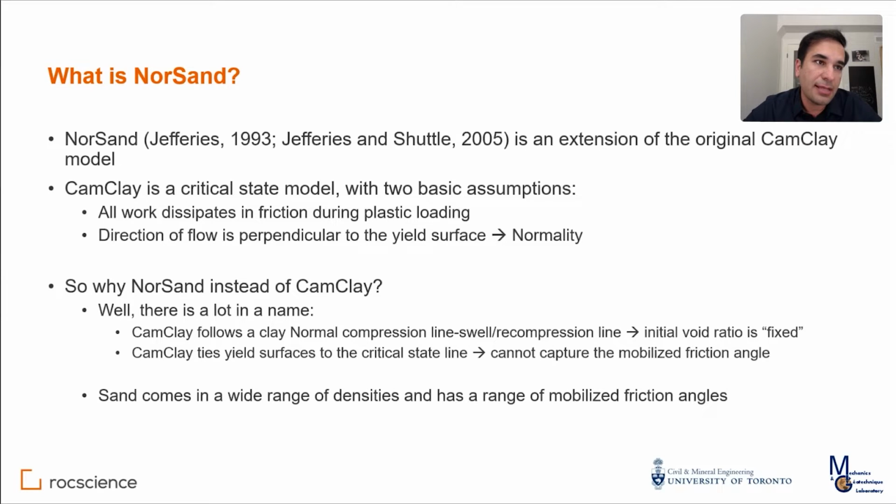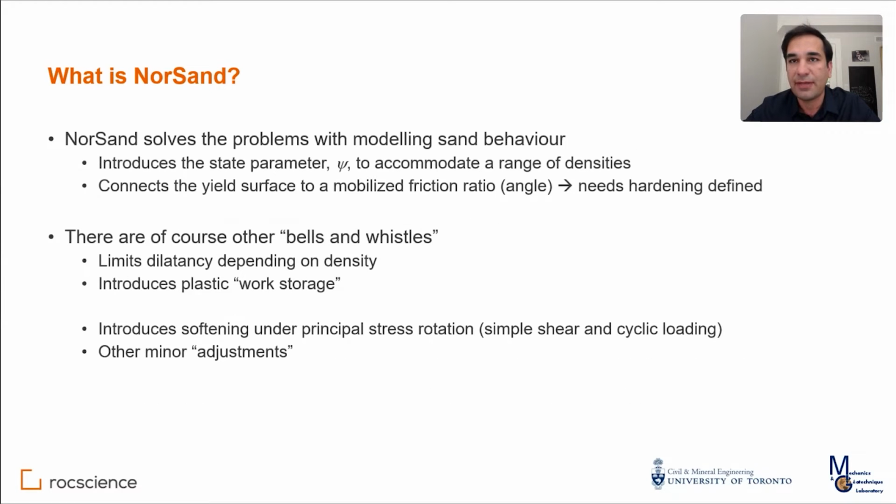When it came to sands, even though you can try to fit CAM-CLAY to some sand, loose ones usually, you cannot capture the wide range of behaviors that sands have, because you can get sands loose and dense and everything in between. They have different mobilized friction angles, and CAM-CLAY is not quite capable of capturing those.